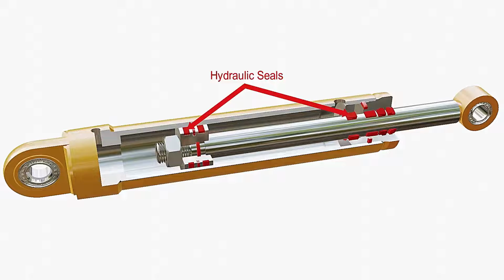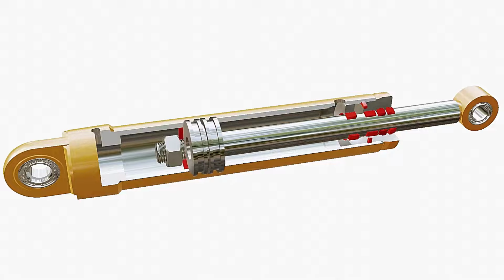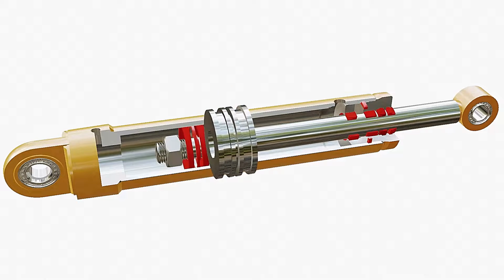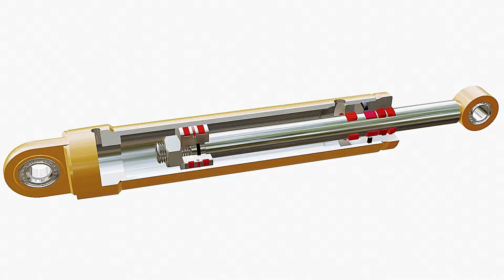A set of circular sealing rings are used in the interface of metals. These rings are assembled by making grooves in the metals. The seals used between the surfaces of metals in relative motion are dynamic seals, and those acting between two surfaces at rest with respect to each other are static seals. A piston seal acts as a pressure barrier between two chambers separated by a piston.